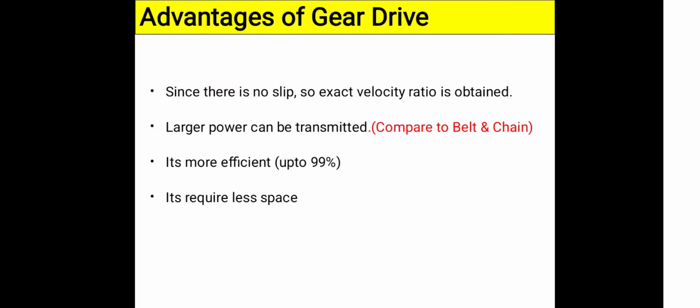There are some disadvantages also. It needs special machines and tools for manufacturing the gears. Then there is high maintenance cost, and chances of vibration and noise during operation. It requires precise alignment of shafts for power transmission.